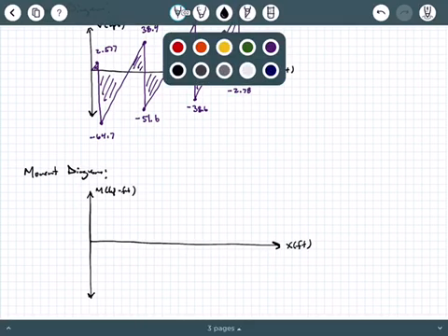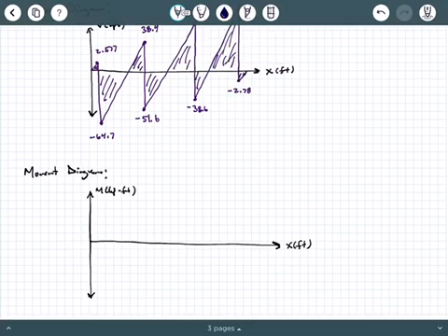You're going to have to use similar triangles in a few spots. So this first dimension line right here is 1 foot, and then the dimension line on the shear diagram from point to point, you're going to call this maybe x, and then call this other dimension 40 minus x, or maybe call it x1 just to give it a different name.